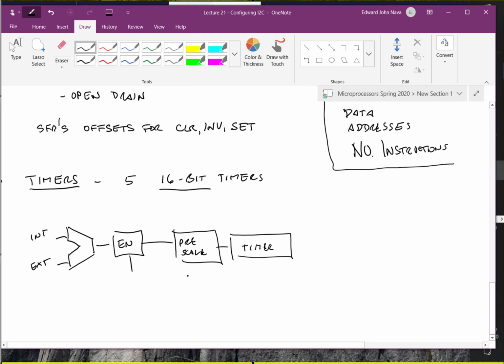And this is basically a divider that will slow down the clock appropriately. So we have 2 types of timers, type A and type B. We have one type A, which is timer 1, and that has limited divider capabilities. And we have a comparator, and we have our period register. And these compare. So this is a reset, and this is an interrupt flag.